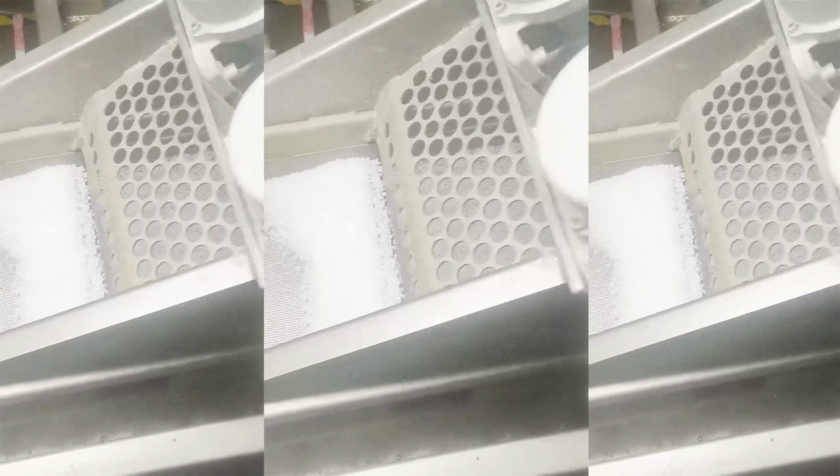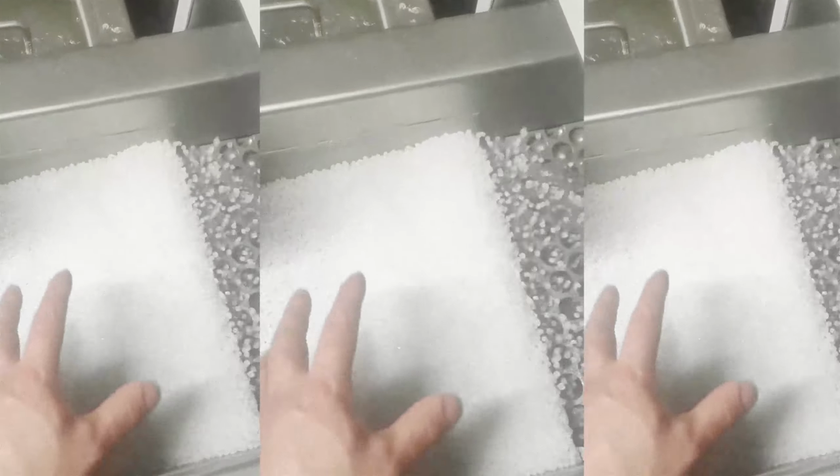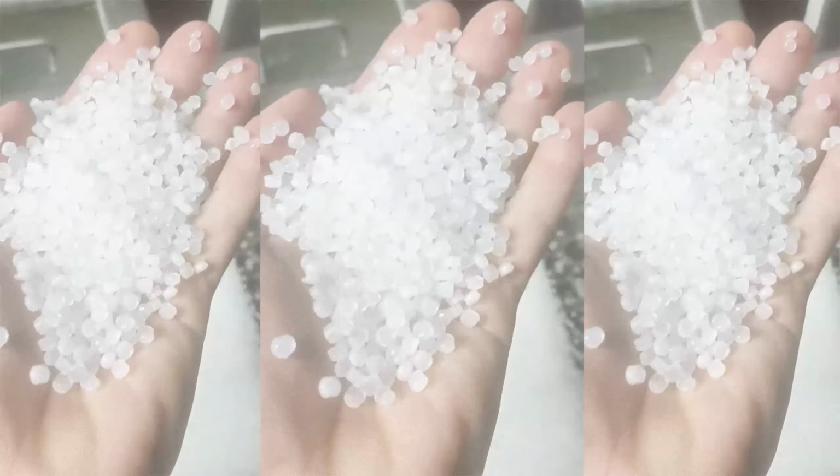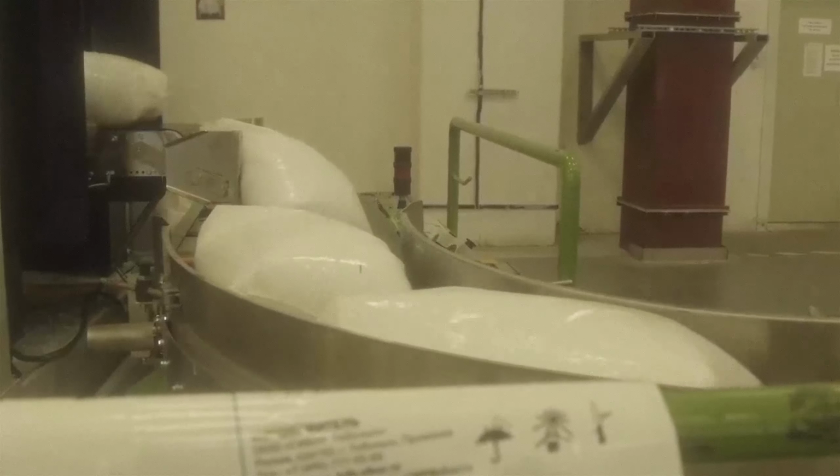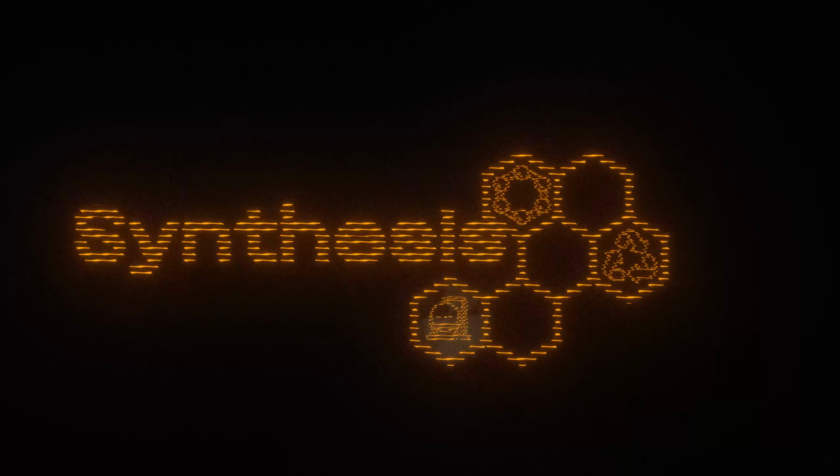After polymerization is complete, the polymer is purified and dried. The polypropylene is then cooled and cut into small granules with a diameter of 2 to 5 millimeters. These granules are a versatile raw material. They melt easily, are easy to transport, and can be mixed with additives in subsequent stages.